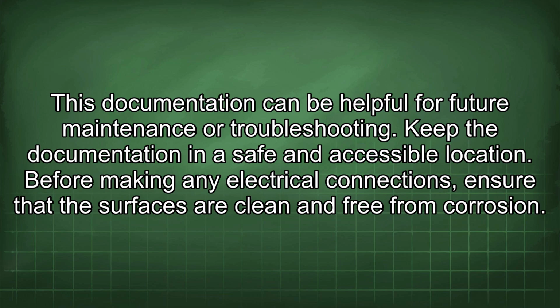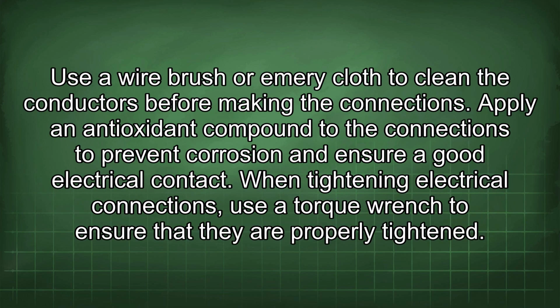Before making any electrical connections, ensure that the surfaces are clean and free from corrosion. Use a wire brush or emery cloth to clean the conductors before making the connections. Apply an antioxidant compound to the connections to prevent corrosion and ensure good electrical contact.